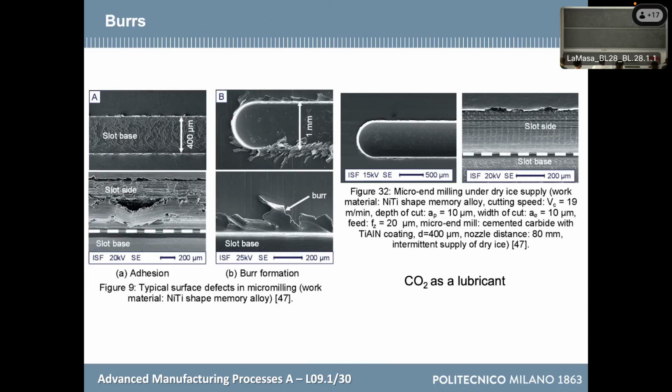Some microns, let's say. Then burrs or flashes. In mechanical terms, this is a burr. When it comes from a thermal action, sometimes it is called flash, or even when it is made of plastic. In any case, these things are really detrimental because, as you can see here, sometimes they are even bigger than the features that we are machining. So there are some solutions. A simple one is passing again on the same surface at a 0 depth of cut so that you remove it.